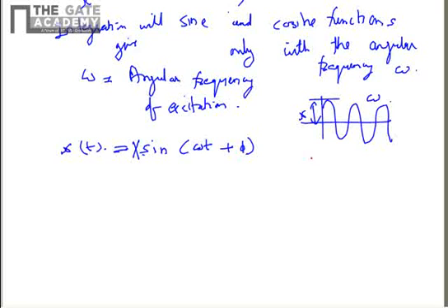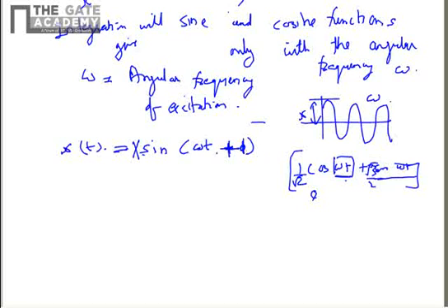This phase phi can be simply understood like this: if you have cos omega t plus sine omega t plus something else, and some trigonometrical quantities, when you sum all these things and simplify, you get a quantity in the addition here. So you will have, say, half, 1 by root 2 cos omega t, and root 3 by 2 sine omega t, and this will be equal to cos 60 sine 45. When you sum all these things, you can relate all the complex combination of cos and sine into a single sine function having the same variable, that is omega t here, plus a phi phase difference. So this is a solution that we can assume which will be the solution of forced vibration.